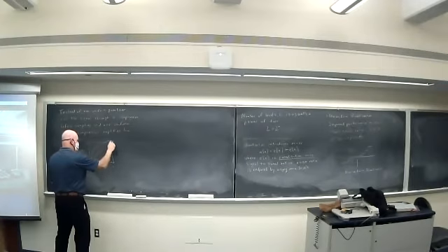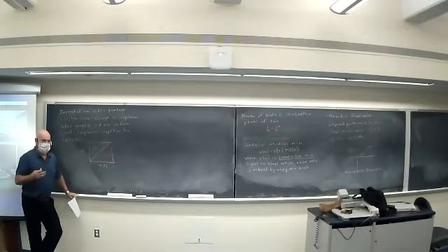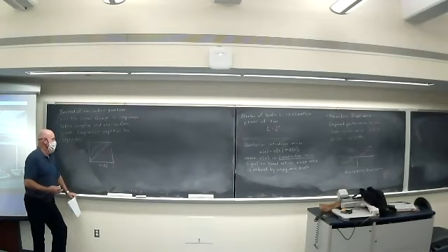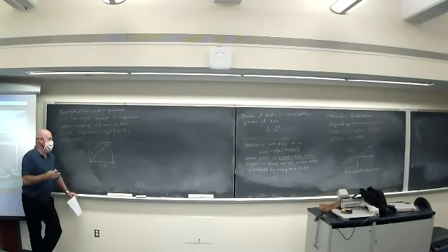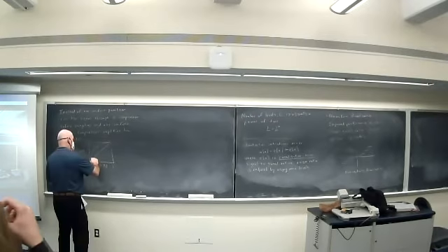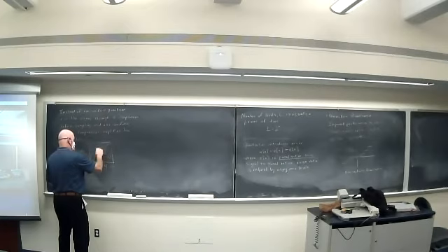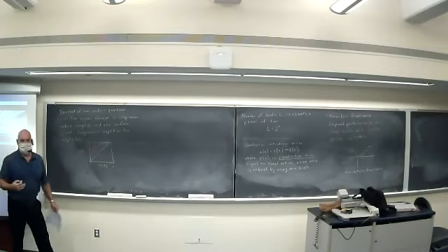This would be just linear amplification, which is often what you want. You make a big deal all through electronics of linear amplification, no distortion. Here we're deliberately distorting the signal to get better performance. We have to undo this to get back the original sound. That's done with an expander, the opposite circuit that we would use at the receiver. We could use any sort of curve that has this general shape, and then use the inverse curve at the receiver to undo the distortion.